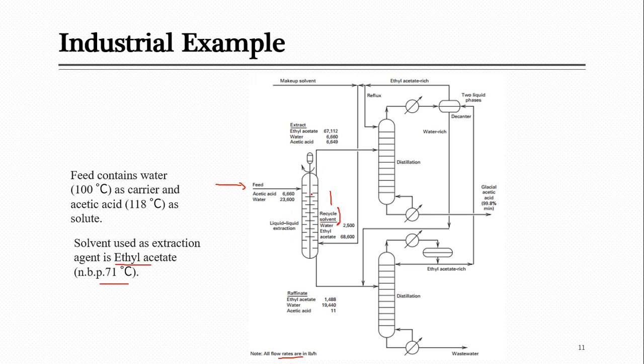This is one of the main systems in which you are providing mixing with the help of mechanical agitation. We are mixing, rotating this main system, in which there will be discs inside. You can see in your book that details are given; I think this is 5 meters high, and so on. When this rotates, those discs rotate and your feed comes in contact with your solvent. When they come in contact with each other, definitely acetic acid will be extracted, or attracted towards this ethyl acetate, and it is transferred from this towards ethyl acetate.